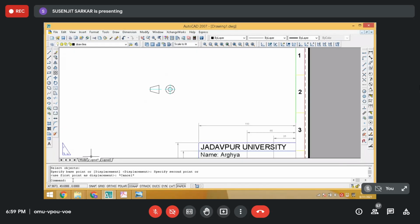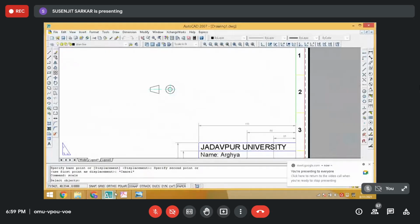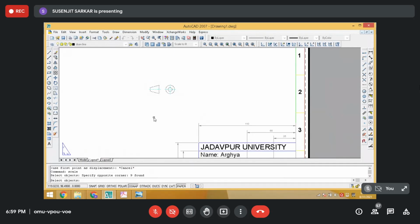What can we do? We can scale. Go for the scale command. Select object, select all. Right click, specify base point.